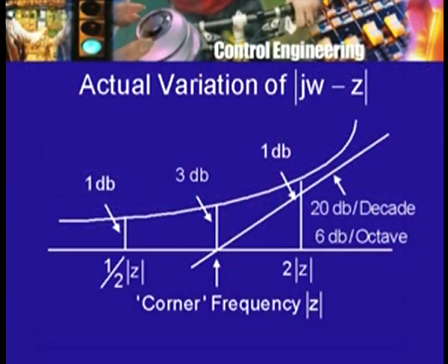So, let us say here is the low frequency approximation, which is just a horizontal straight line because the dB gain is constant, equal to the DC gain. Here is the high frequency approximation, which is intersecting this line with this. Then what is the value of omega corresponding to this point? Now, this is the low frequency approximation, this is the high frequency approximation. So, what we mean is, as omega tends to 0, we are getting closer and closer to this curve, and as omega increases to a large value, we are getting closer and closer to this curve.